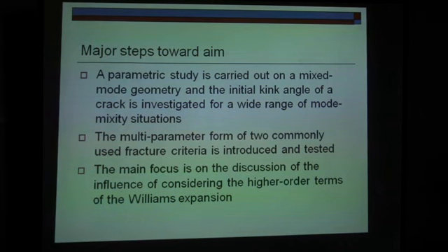Then we use the multi-parameter form of two commonly used fracture criteria. The first one is maximal tensile stress, and the second one is strain energy density. And then we discuss the influence of considering the higher-order terms of the Williams expansion.